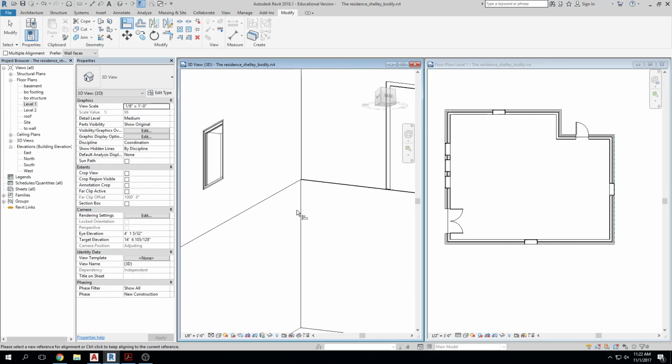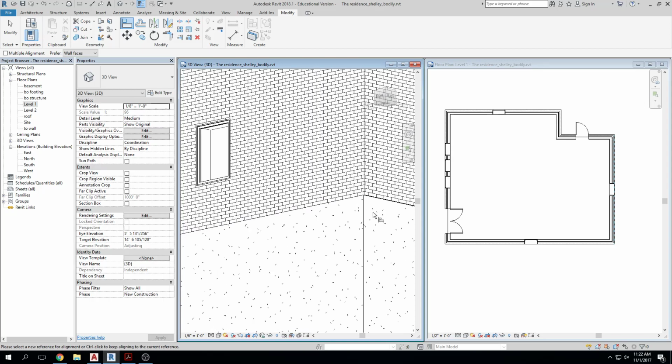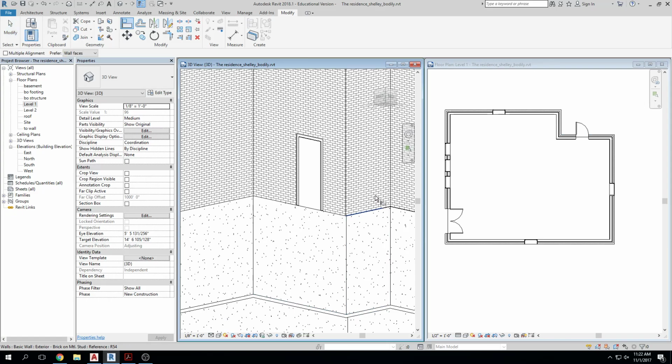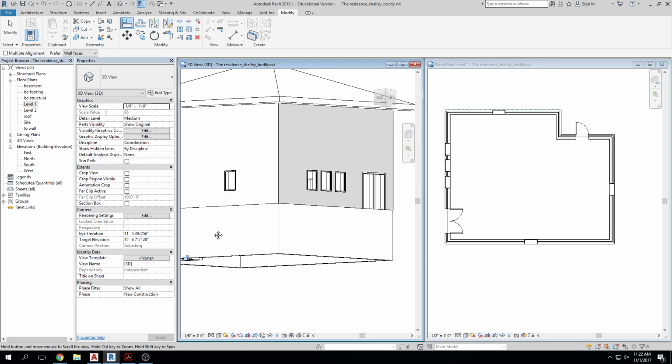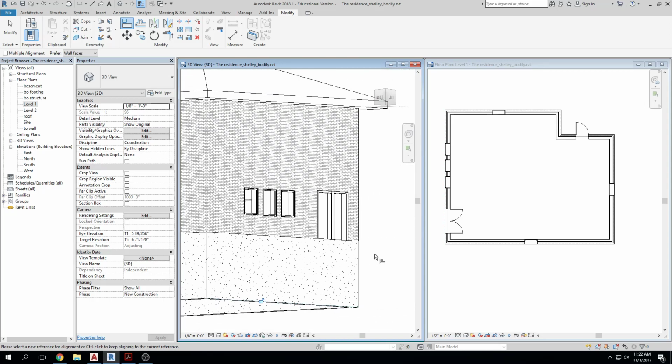Okay. Of all the walls that I usually generate, I would say 99% of the time I have to align my foundation walls after I generate them. Okay. And then you're just going to go around, AL, click, and you hover maybe near a boundary, click, and it aligns, right? AL, click, and click. Okay. AL, click, oop, AL, click, click, there we go. So we just go all the way around. Luckily I don't have very many walls. Click, click, make sure I get it on the right plane.